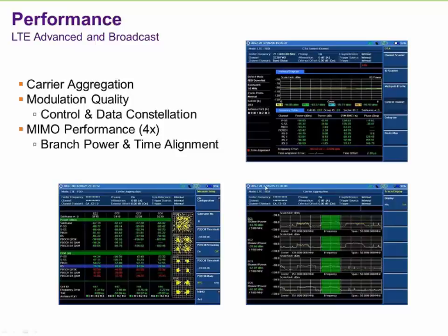Now, on the control channel, the greatest use of it is to actually look at the polarity of the two antennas. Example, transmit 0, transmit 1, oftentimes are plus 45, minus 45. And what you can do with this, if you have an antenna, as you rotate it 90 degrees, you should be able to see that the amplitude changes position as to who's stronger. There was one class I was giving inside the room and saw an 11 dB difference.